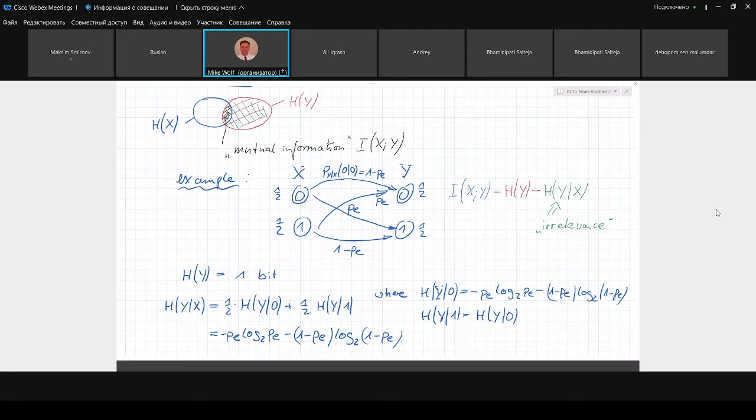But we don't get this just without any effort. We need strong, powerful channel coding. So we have original information bits. Let's say we have statistically, just as this example, 500 information bits. And then we append 500 redundant bits. So we have redundancy, but this is useful redundancy. And then we do this with a strong encoder, with a powerful encoding scheme.